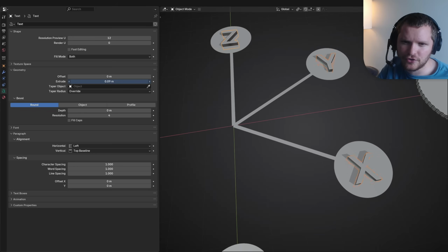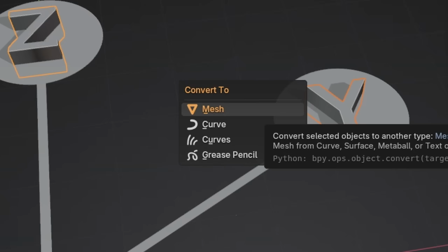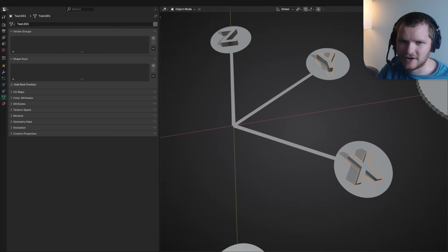Yeah, hold down Alt while you do this, otherwise it's only going to affect the active object. And I'm just going to make this super tall. We're then going to run the convert to mesh operation. All of these are meshes that I can Control J join together.